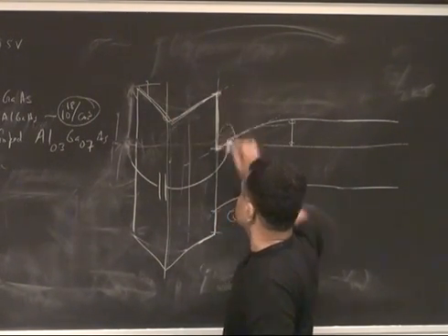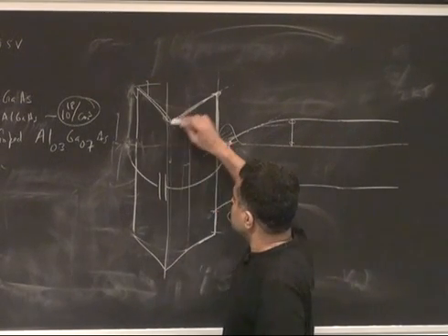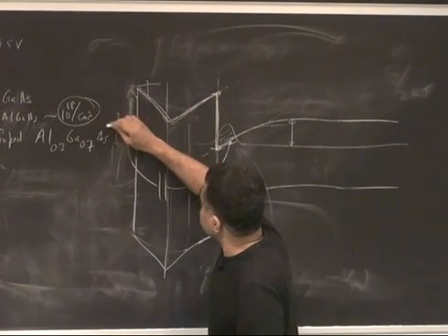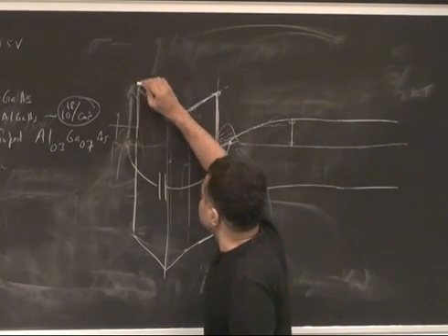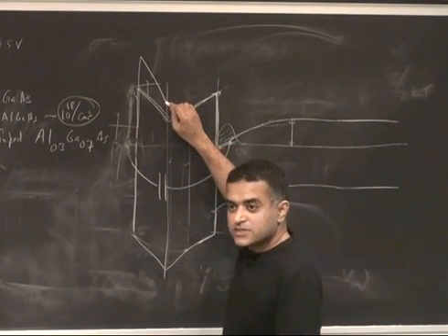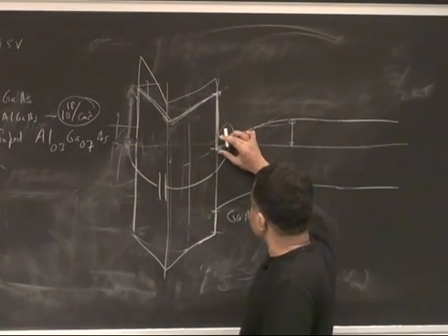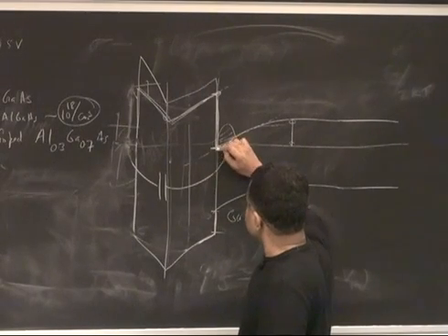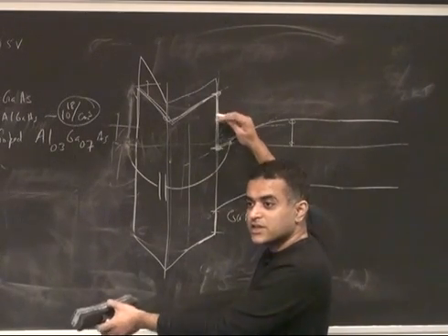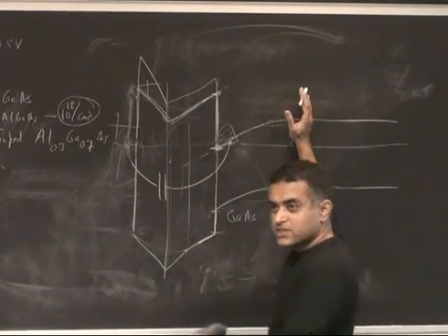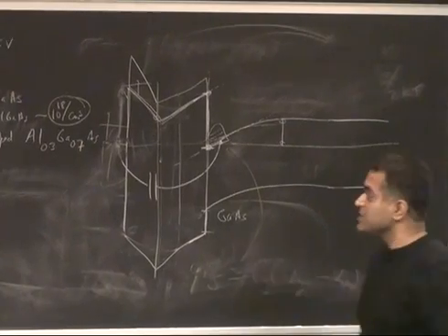I mean, the band offset doesn't change with gate voltage. No, so essentially what it does is, the Schottky barrier height doesn't change with gate voltage. It starts pulling the whole thing up now. Does that make sense? So you can see you're pulling the conduction band minima here above the Fermi level now, and then you're emptying out the electron gas. That's the switching off of the device.